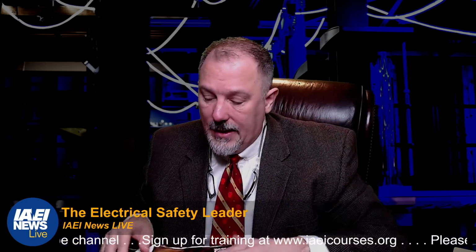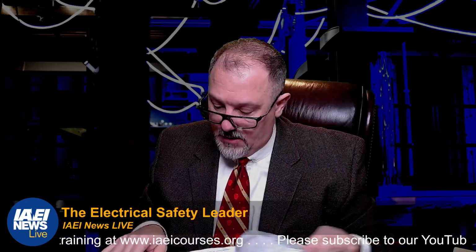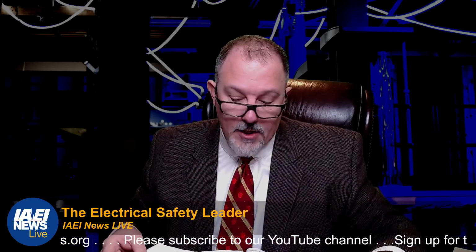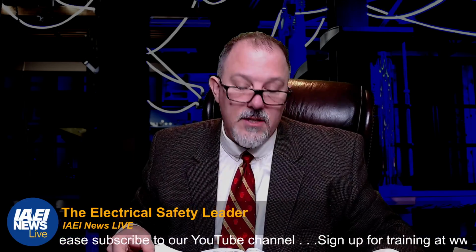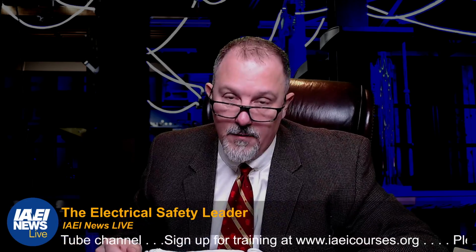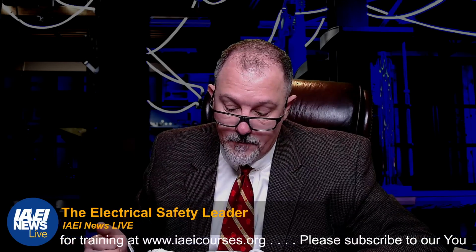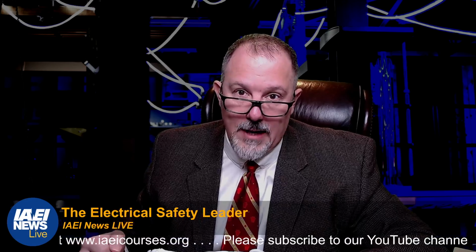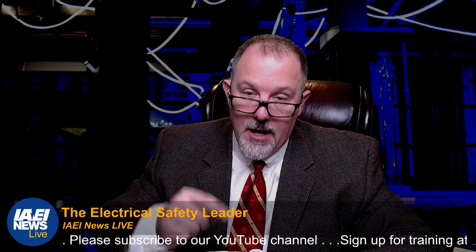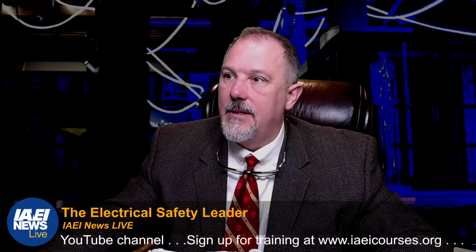When we got into the changes that we see in Article 220 for load calculations, we made some changes in the VA per square foot, not the watts per square foot. Because we don't size equipment based on watts, we size the equipment based on VA. So Table 220.12, we had this discussion considerably in length, that what we're dealing with is watts and not VA. And these lighting solutions do not have a unity power factor like we're used to with incandescent lighting.